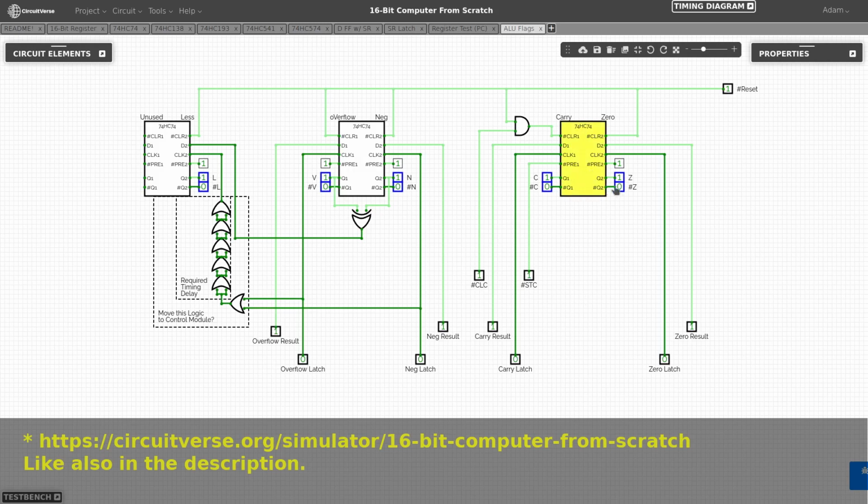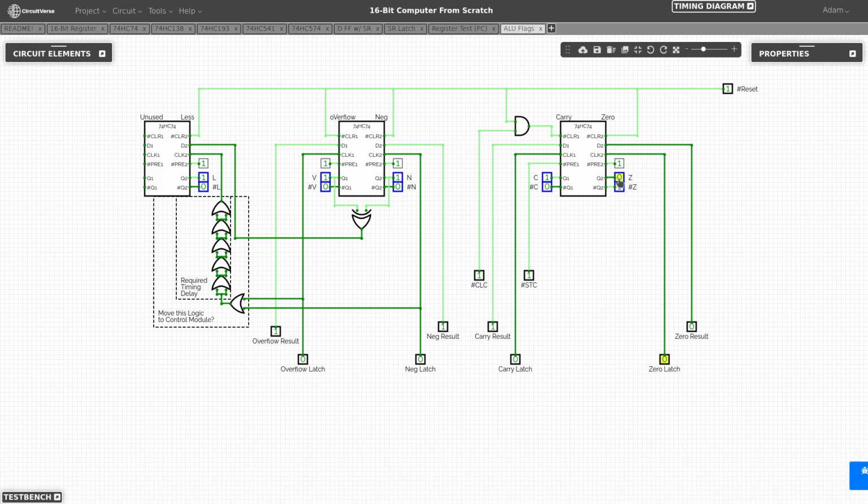And so what you can see here is I've got several control signals coming into this. I'll get to what's going on over here on the left in a minute. But if my 0 result is 0, when I latch that, you can see my 0 and not 0 change immediately. And conveniently with the flip-flop, I have both the Q output and the inverse Q output delivered to me right from the IC. So I don't have to do anything special in order to calculate the inverse Q.